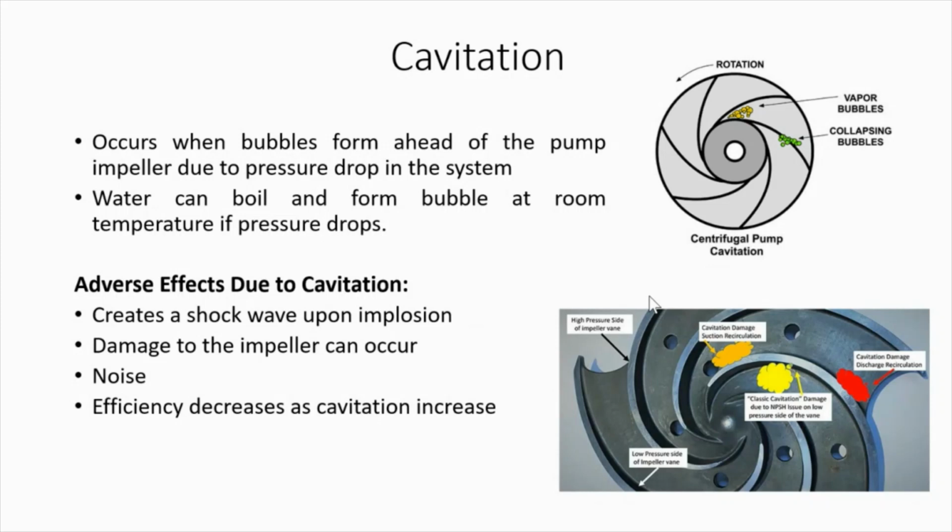So what's happening when there's a pressure drop? I'm sorry, when there's a pressure drop, the liquid has its own vapor pressure. So what does it want to do? It wants to vaporize itself, because its vapor pressure just decreased. So these localized pressure drops create these localized bubbles.